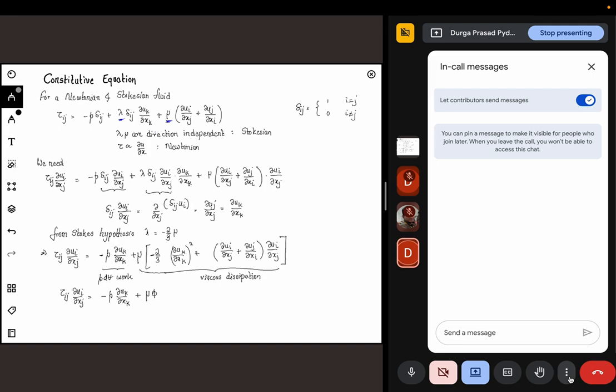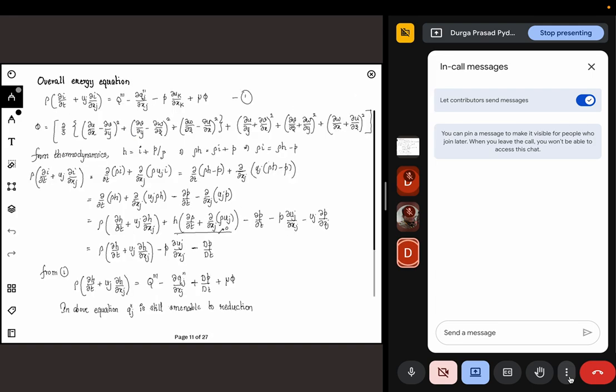When a fluid passes at high speed through a duct, heat will be internally generated, purely because of the viscous nature of that flow. This term we denote with phi. We can substitute both terms into the previous energy equation.